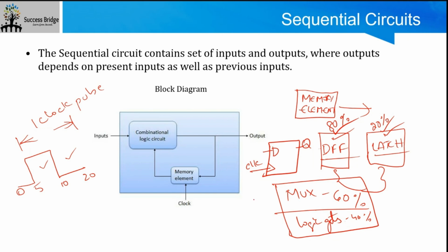Okay, so when you provide clock, to the active edge, the positive edge of the clock, this particular D flip-flop, okay, this is a positive edge D flip-flop, which means the data gets toggled. That means you are giving input at this place, which is a 1, let's say 1. 1 will be stored in this flop, as well as come to this position of Q when you give one clock pulse, and that too a positive clock.